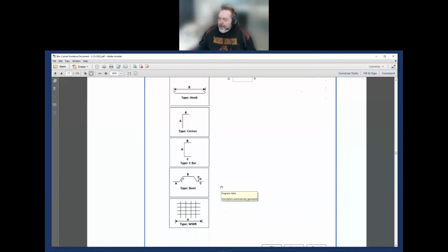So you may have a positive moment region where you want the lower part of the crank bar in the positive moment, and you want the tails up to look like those bars in the W box culvert. You'll need to break those into individual straight segments because you cannot flip the bar over.